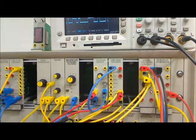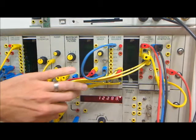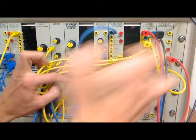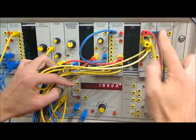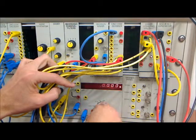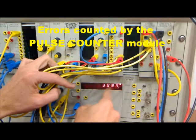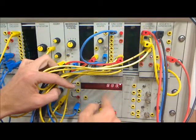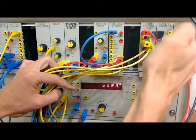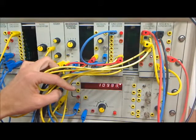Now we'll just move the camera down, pan down. Now you can see some errors being counted on the pulse counter. I've taken that error signal from there and input it to the pulse counter, not the frequency counter, the pulse counter. And you can see it's counting the number of pulses, counting up rather quickly, because we haven't synchronized our local sequence yet, so we still have a number of errors.